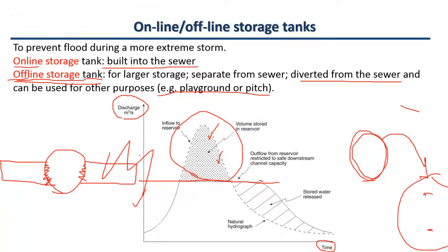Based on health and safety, once you are going to design, health and safety is a key point that you need to make sure is respected. So obviously, if there is something a few meters deep, you should say, okay, I'm not going to use that one, and try to make the maximum height as high as the normal human depth, let's say a minimum of 1.5. 1.5 is a safe depth. If someone dropped into that water unintentionally, it's not life threatening. So this is really, really important.